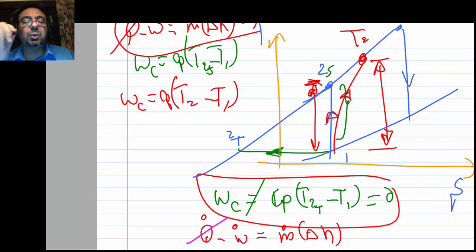We want to do this as smoothly as possible, and they managed to do it isothermally. So how do we do it isothermally? We have to compress very slowly so that the cooling can catch up, and you need a very efficient cooling. They managed to cool it by spraying water and letting the water absorb the heat. Therefore, the air will get cooled very quickly. Right? The water will get a little bit hot, but then they figure, well, we can use the hot water later on, extract the energy from it.